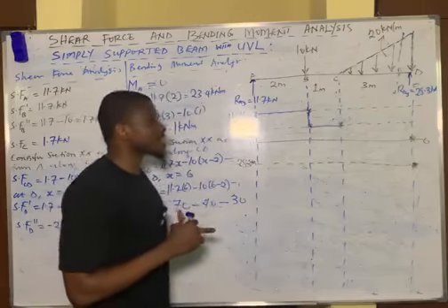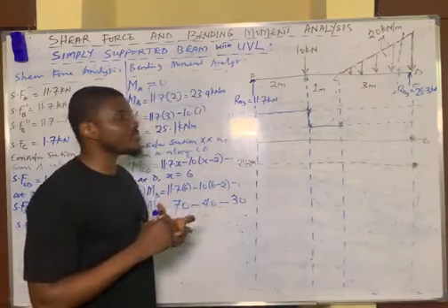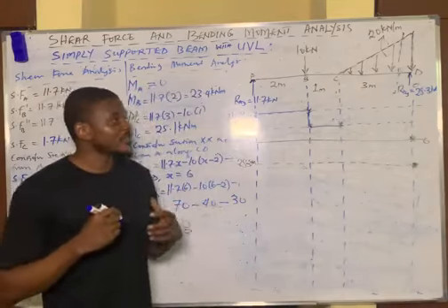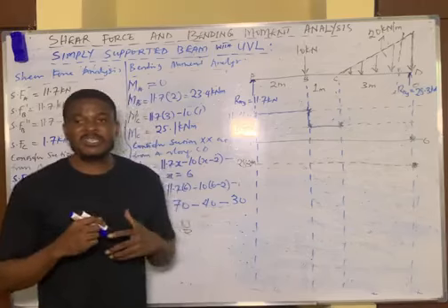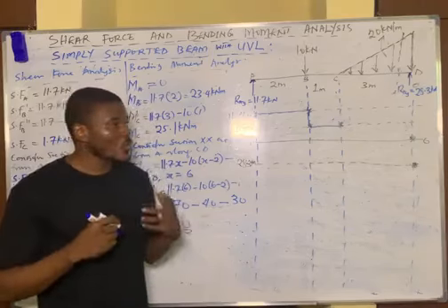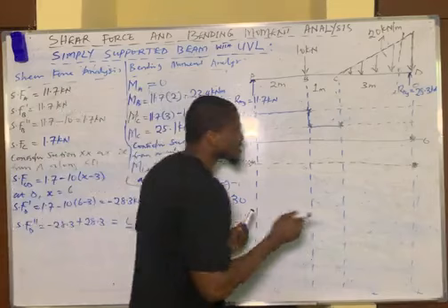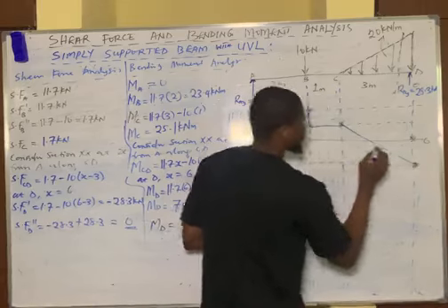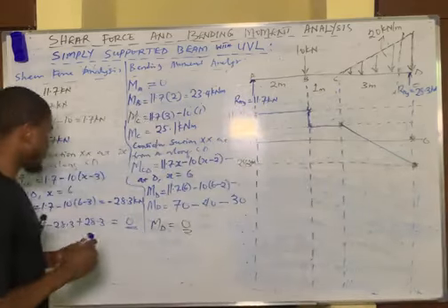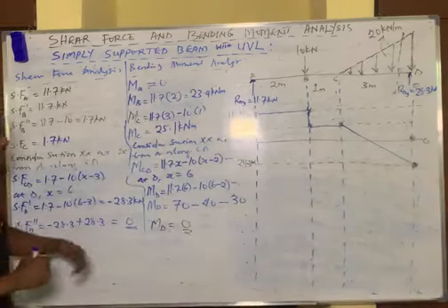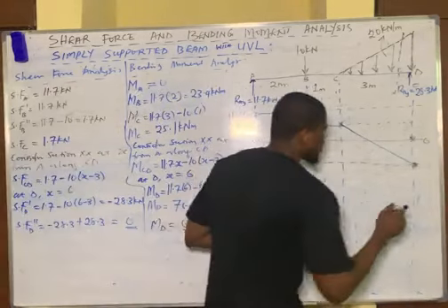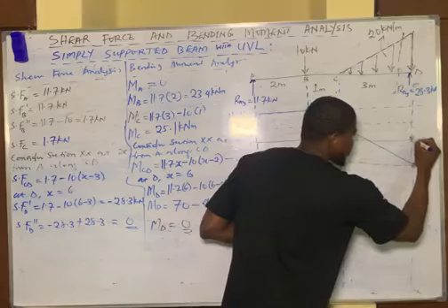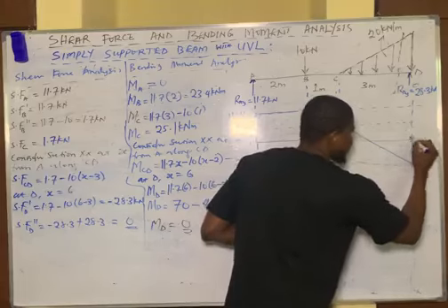The shear force diagram for a uniformly varying load is simply a slant line to connect each of the points. So you draw a slant line connecting these points to these points, and you have this. And finally, shear force at point D becomes 0. So finally, at point D, a point load once again. So you simply connect with a straight line, and that's it.